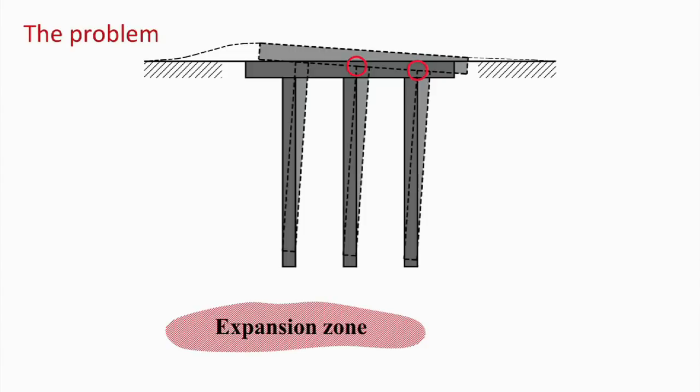Now, this is the problem. I have some expansion zone. Well, it can be an expansion, or it can be a contraction, it can be anything that actually increases volume in any manner. This is the idea. And the question is, how will a pile foundation react when you expand an area here, in this case, below the tips of the piles, which happens typically in buildings founded on piles in many cases when you apply compensation grouting.